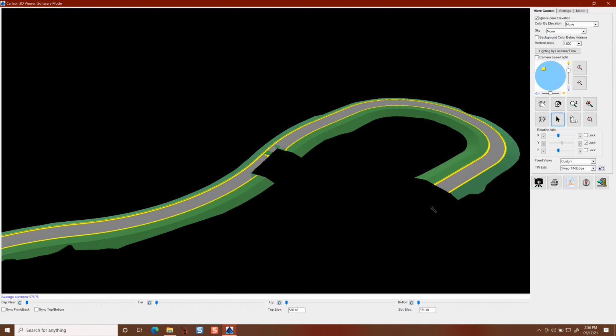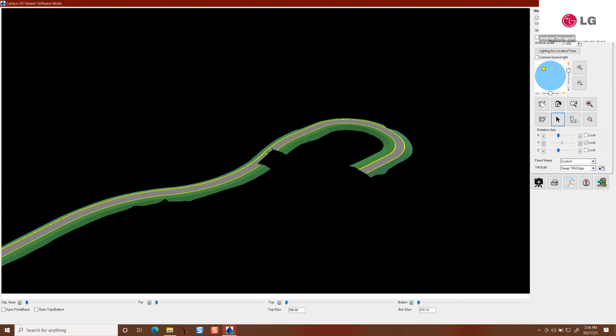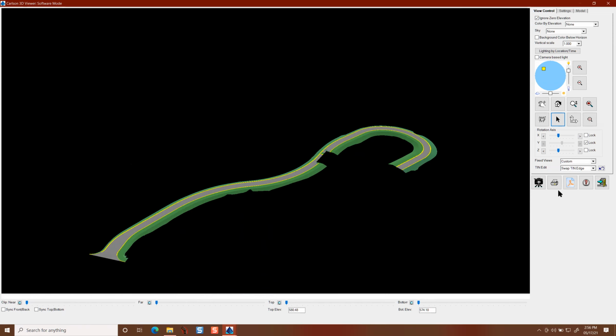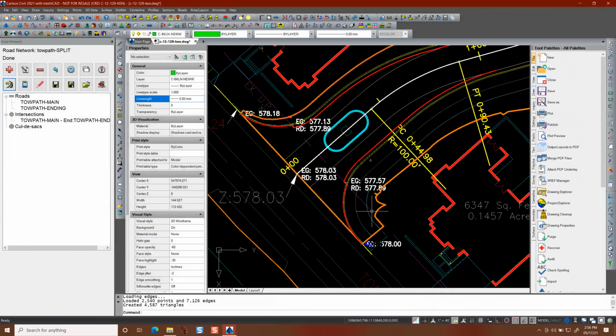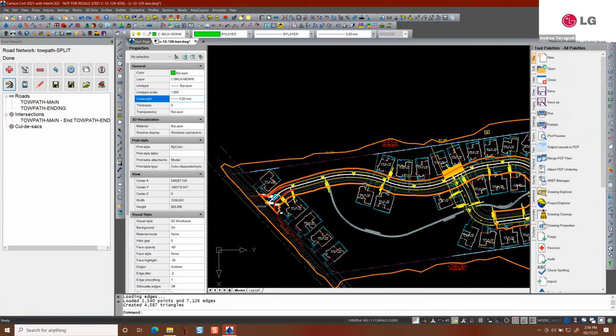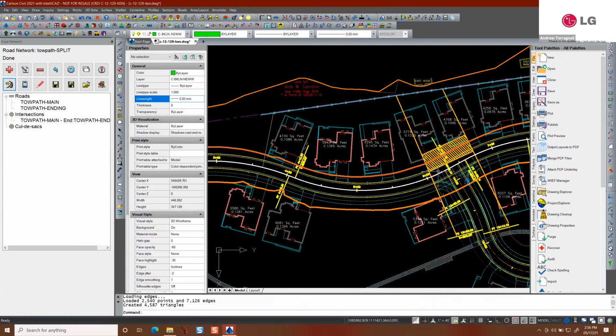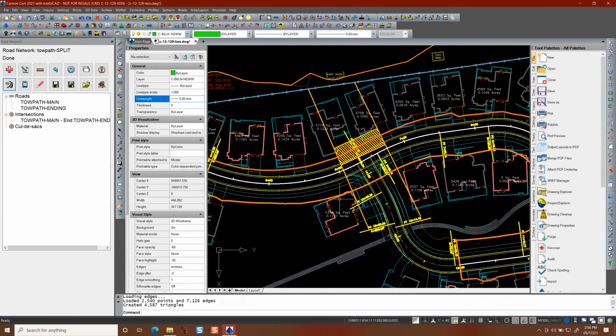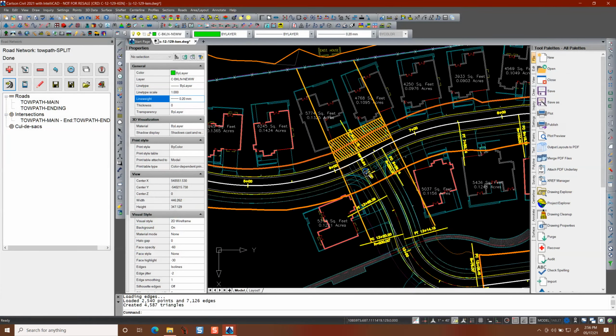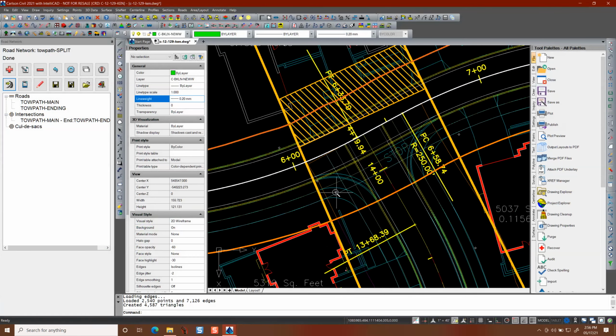And so to process intersections, what happens is it builds all of the 3D lines for each road, and transitions it together. It builds them independently, and then it goes back and examines all of these things that it finds that edge of pavement, which is the point we said we want to use in our intersection processing, to blend. In fact, if we had said use the sidewalk point, the pavement would just go straight across, but the sidewalk and everything behind it would be the line.